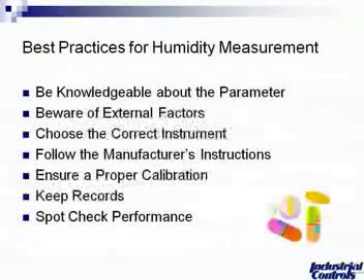So we're going to talk today about the best practices for humidity measurement. Greg is going to speak to understanding better about humidity and the effects of its parameter. It's just like picking out a flow meter or a temperature sensor. The more you know about the technology and what's available, the better chance you have of picking the right technology. Be aware, of course, of external factors which could affect the selection. Choose the correct instrument. Follow the manufacturer's instructions. Ensure a proper calibration. Keep records and spot check performance.